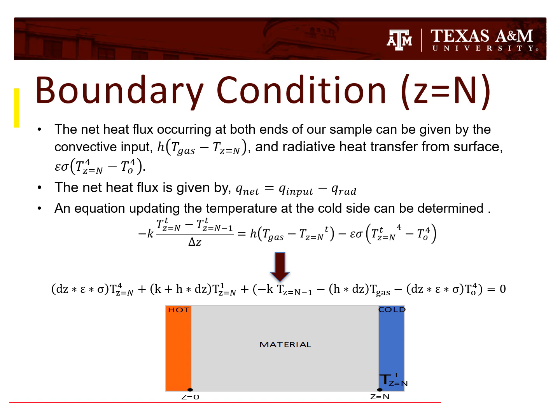We can apply Fourier's law of conduction to determine an equation that updates the temperature at this boundary for each time step. Rearranged into the form of a fourth degree polynomial, we can solve this in MATLAB and help model the temperature distribution within our sample.